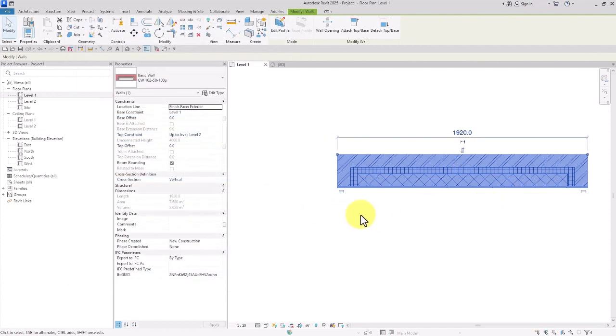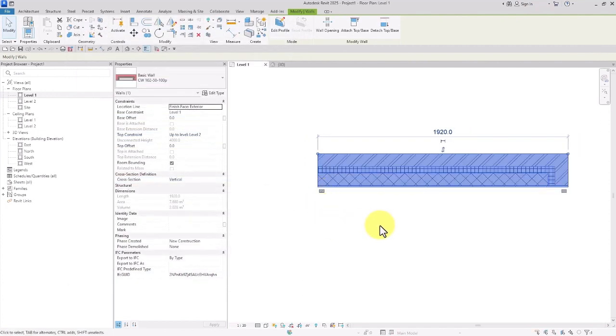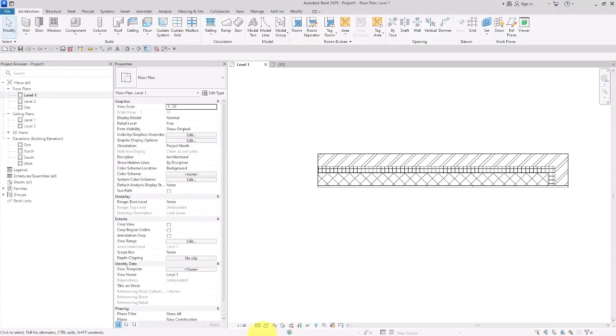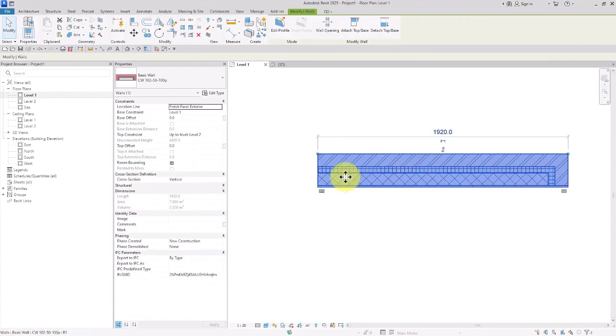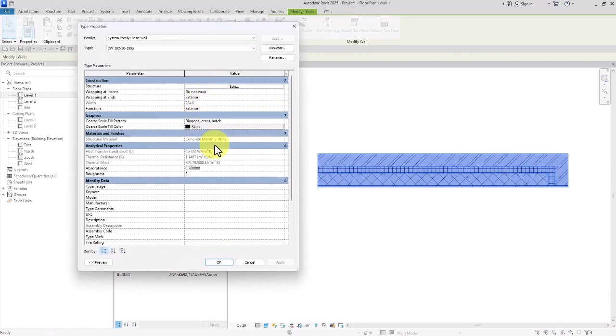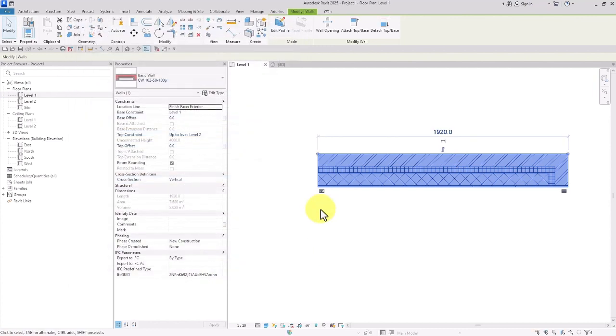This was the case in previous versions, but now, as I said earlier, we can control the wrappings on both sides completely separately. This is, again, a very useful technique when it comes to working on walls containing both frameworks and finishing works. We can, for example, easily wrap up one side and not the other one. And the limitation that I've mentioned just now is gone in the new version.